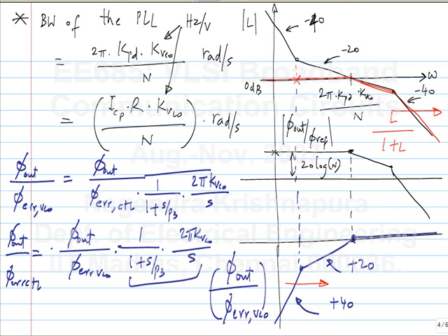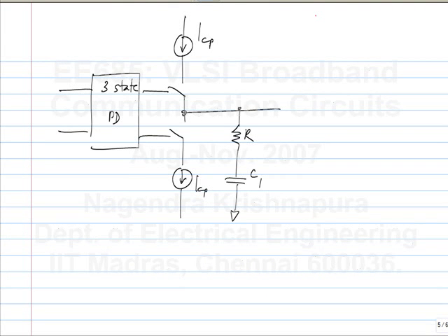Now occasionally you also use it to, you have a noisy oscillator and you have a cleaner oscillator in the phase locked loop. So you can clean up the noisy oscillator using this clean oscillator. In that case, you use a very low bandwidth so that it doesn't track the input noise of the input oscillator, but it tracks the noise of the VCO inside the PLL. Okay. So it's all just to do with which one has more noise. Okay.